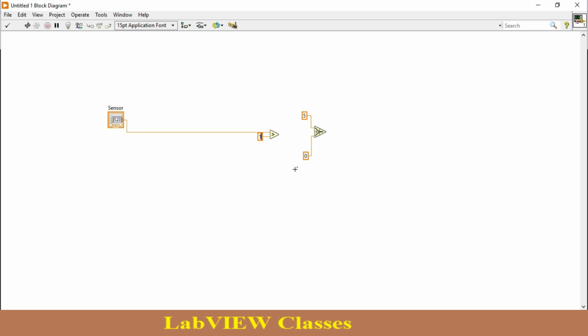Okay, but like in our electronics project, the IR sensor module will generate 3.26 volt when my hand is in front of that IR sensor. So it is up to me. First I have to check what is the value generated by my sensor from the data sheet.